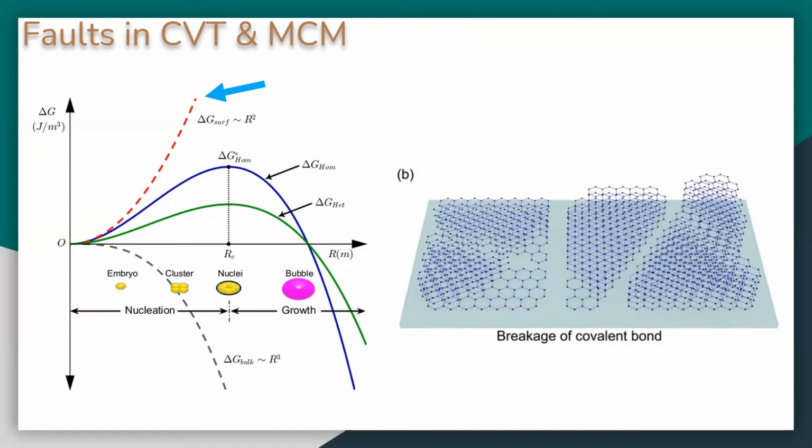So there are some issues that can occur when growing these crystals. The most commonly encountered problem in CVT is the excess nucleation that leads to small crystal clusters and a slower growth rate. This usually occurs when a larger crystal is needed, and currently the way to address this issue is to use a seed crystal to suppress nucleation and include an inner tube to use as a separator and flow restrictor. And for chromium thiophosphate, this is not too much of an issue since only small crystals are necessary for study purposes. It's not being used in application yet.